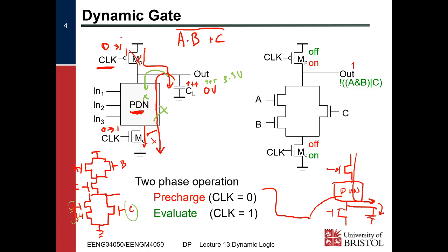So that's why it's not beneficial to just swap it the other way around, because just as much as we can leak charge down to ground, we can also leak charge from VDD, right? The charging rate will be exactly the same as the discharging rate as the previous case, right?